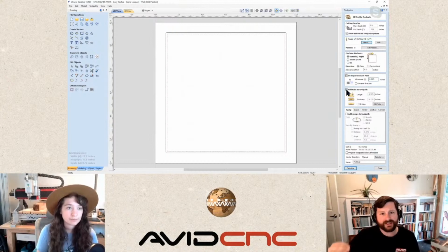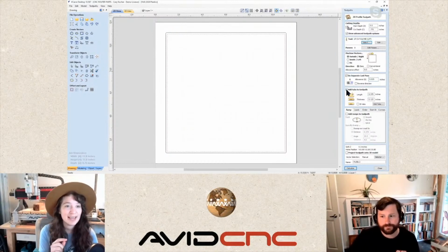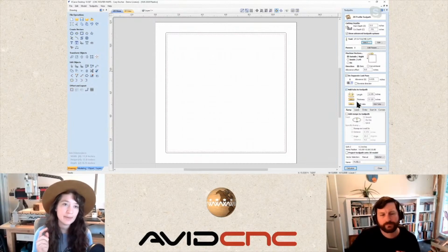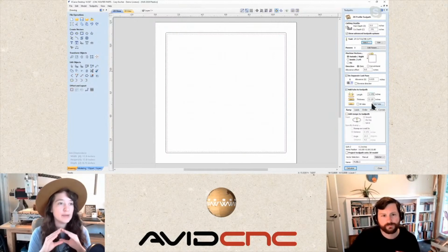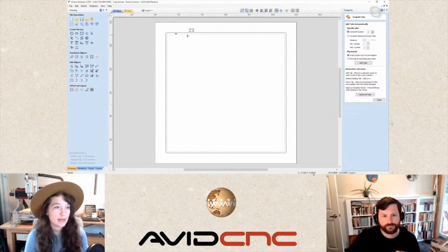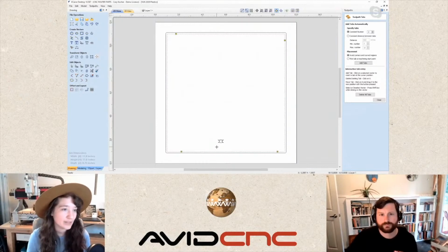And then, Sami, what kind of tabs do you like to use with acrylic? Well, for tabs in particular, I prefer a square tab. And I like to go about an 1/8 inch thick and about 3/8 inch wide. Having the pyramid shape or the 3-dimensional tab, you have a higher risk of tearing out, which I prefer not to. You don't have to worry about grain here, which is really great. So using the upcut, you don't have to worry about tear out on your material. And with your tabs, you don't have to worry about grain strength.